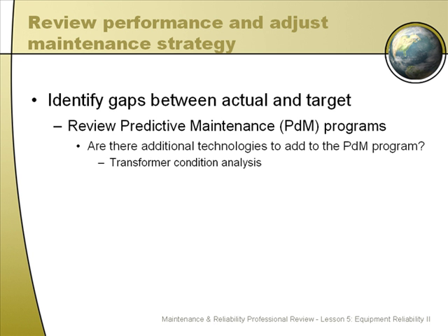Transformer condition analysis is another electrical PDM tool that can be used. Transformers have a variety of different things that can be measured on them, and in certain instances they are key high criticality pieces of equipment in an operation. Generally speaking, they generate a lot of heat, and they have cooling mechanisms inside of them, including lubricants and oils of different types. And some of these things can actually be quite hazardous if they're old, so I recommend that you make sure that if you have a transformer that contains PCBs, for instance, that you don't go tackling this without an understanding of what transformer condition analysis has for hazards and also benefits.